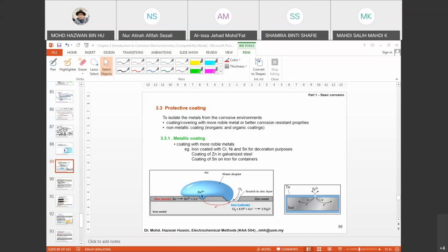Then normally we should apply some methods, like maybe cathodic protection, to control the pipes. So basically, if you ask me, it can work both ways. Normally, as a precaution, we can apply corrosion protection methods before the process and also during the process. And it all depends on the materials and also the types of environment that you're dealing with.